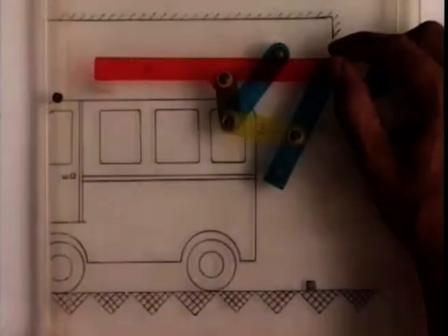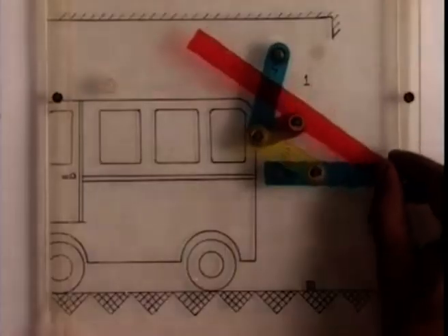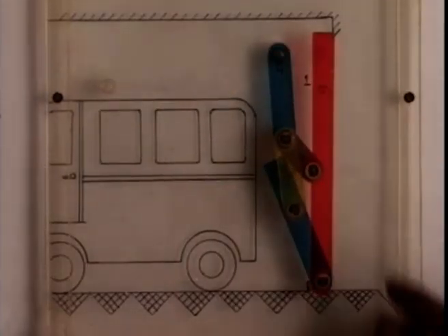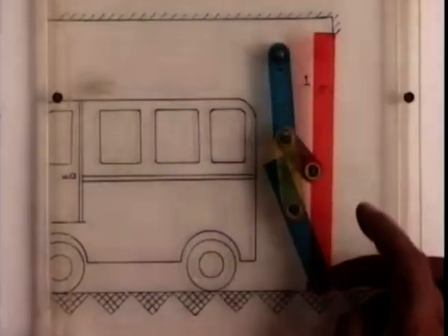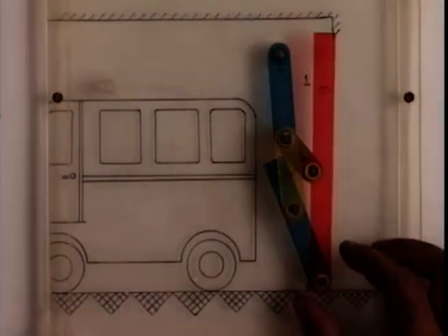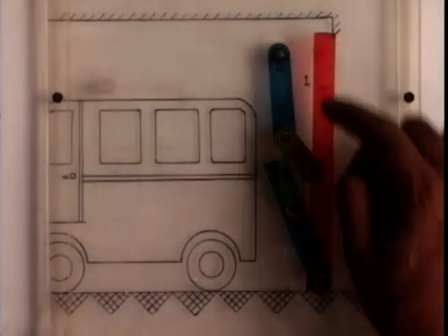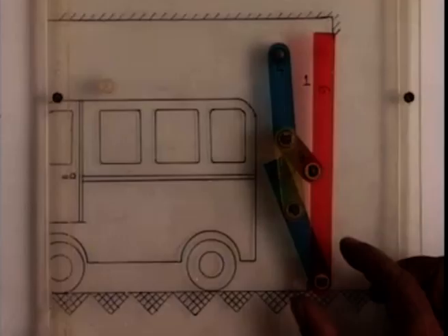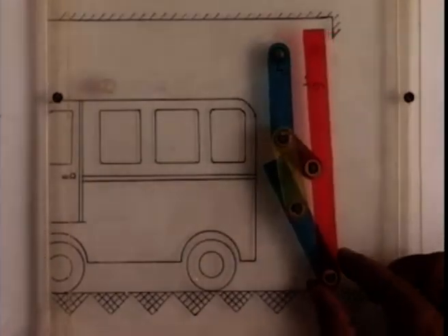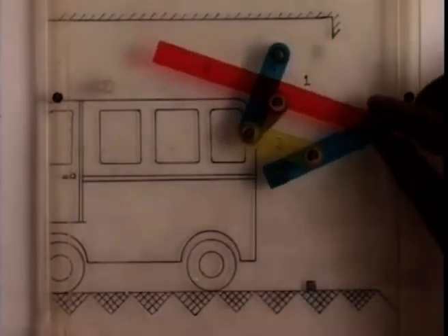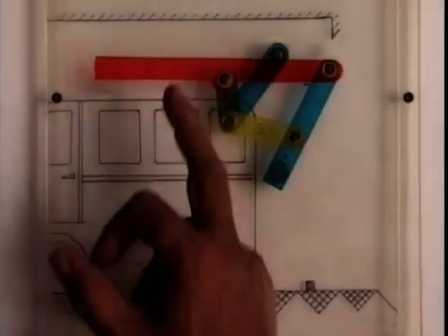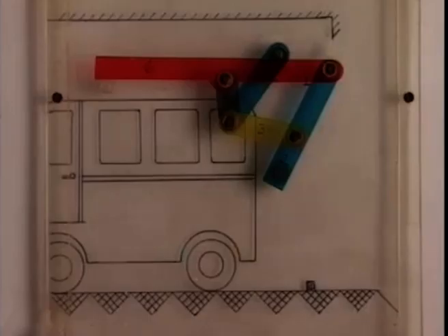Now to close the garage, the door board is moved such that the garage gets closed. So this is again a guidance problem. I want this particular rigid body, that is link number 6, to move from this closed position to the open position in a prescribed manner so that it does not hit the body of the car.